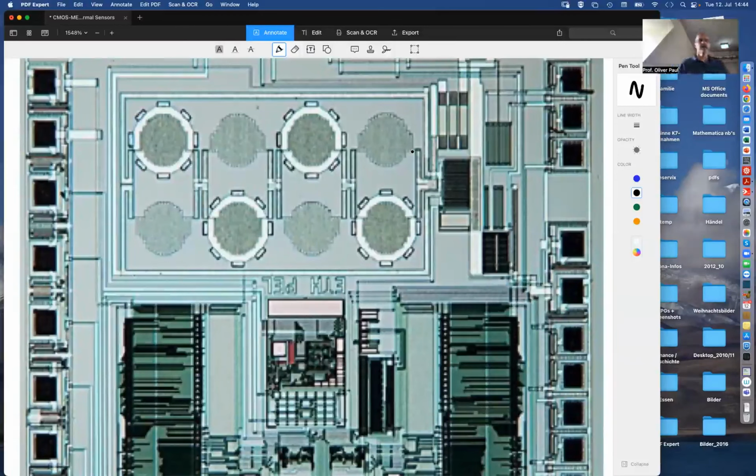Then those are in series, and there are reference sensors that are also in series, meandering through in a common centroid design, minimizing the effect of gradients on the outcome. And those reference sensors are just meanders as they are implemented in the thermally sensitive sensors, whereas here the meanders sit just on the silicon chip, embedded between the dielectrics, and there is no gap underneath.